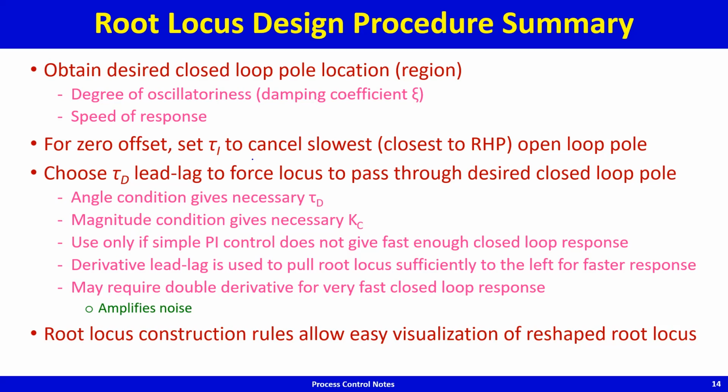So where to place the 0 corresponding to the integral action or the derivative action can easily be visualized by invoking the root locus construction rules and seeing how these rules reshape the root locus depending on where the 0 is placed. Okay, so that's why we covered these root locus construction rules.